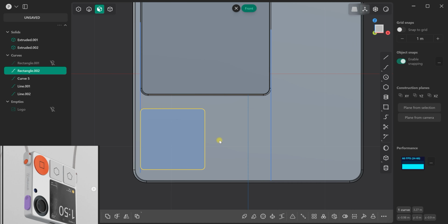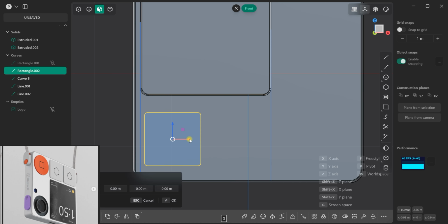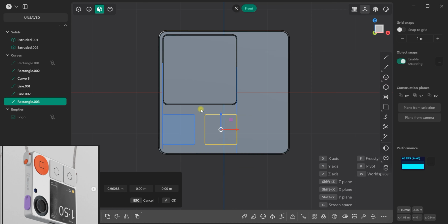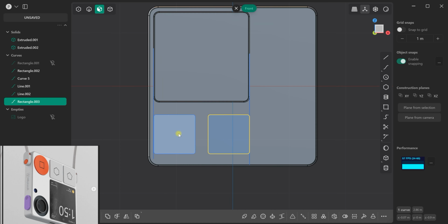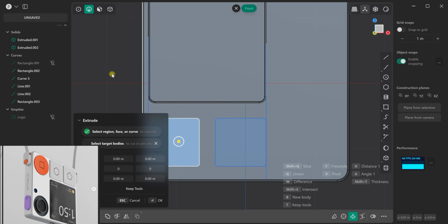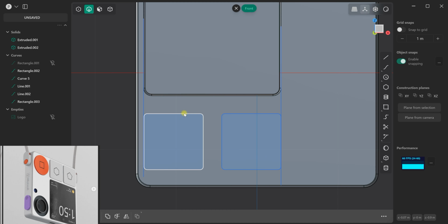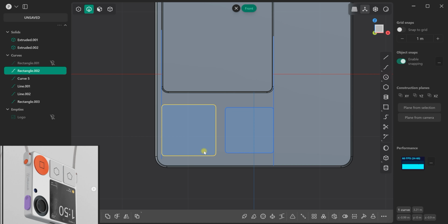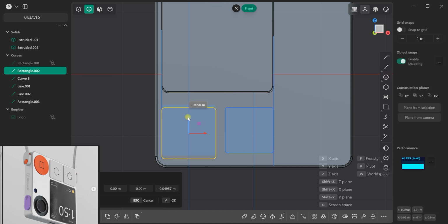Adjust the size. Yes, we're guessing again, but it's gonna look nice. Shift D to duplicate it, move it here. Let's look at the size. And I think we need to resize again. In edge mode, select our rectangle and resize it by pressing S, right? Move it here. Let's bring it maybe down a little bit. Okay, something like that. Okay, to confirm.